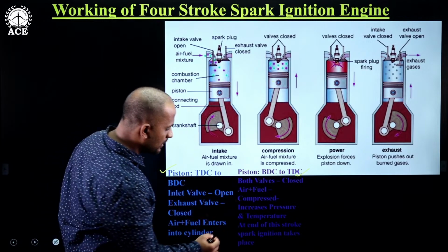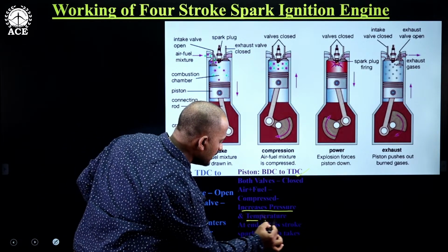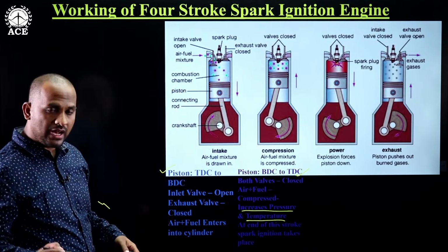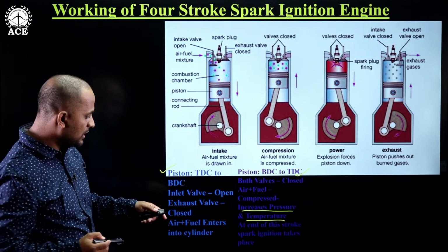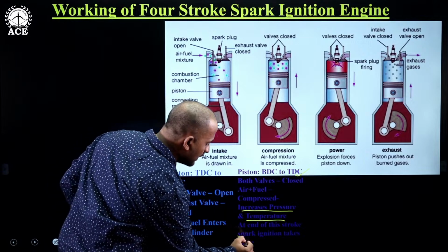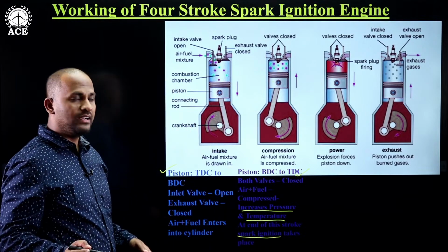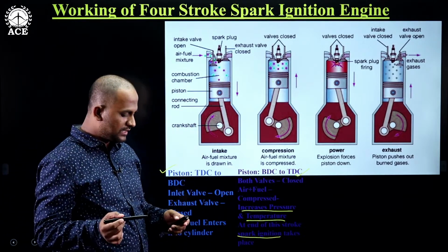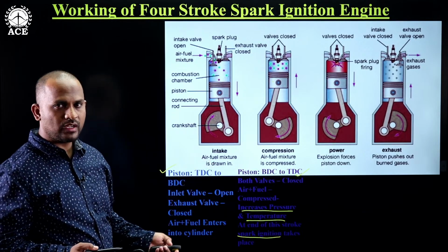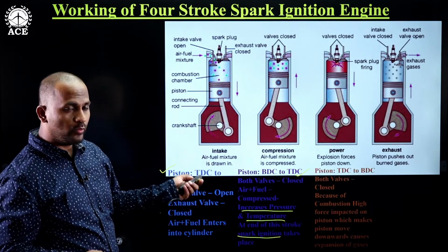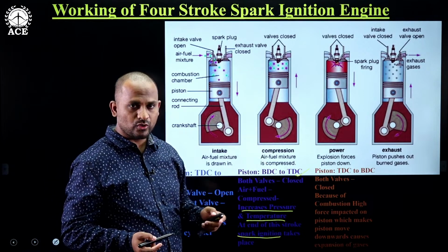The charge pressure and temperature will be increased, and at the end of the compression process, the spark is created inside the engine. That completes the compression stroke or compression process. Now what is the next one? The next one is the power stroke or expansion.